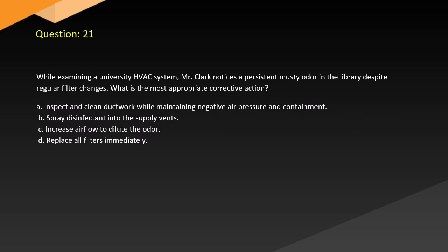Question 21. While examining a university HVAC system, Mr. Clark notices a persistent musty odor in the library despite regular filter changes. What is the most appropriate corrective action? A. Inspect and clean ductwork while maintaining negative air pressure and containment. B. Spray disinfectant into the supply vents. C. Increase airflow to dilute the odor. D. Replace all filters immediately.